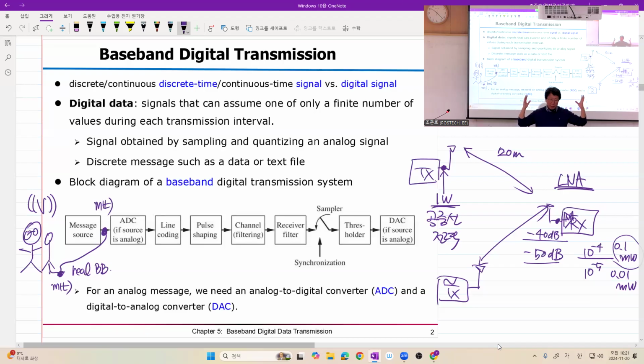So if you look carefully, suppose we have an oscilloscope, what will your current be? Every time an electron passes, you will see a Dirac delta function, right? As I once told you. And even though you zoom out, you will see a lot of very high frequency variations in your current if you hugely amplify the small signal. That actually happens in the receiver's amplifier, because your received signal is so weak.